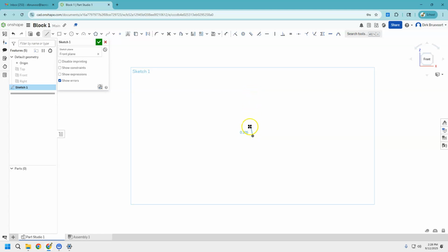Now when I'm drawing, unless I'm drawing something that's curved or angled, I'm going to always make sure that a couple of things are on. When I go up here, I can go a little bit side to side, and it will snap here, and you see it changes color, and there's that little vertical black bar. That means the line is going vertical. When I go over, it's showing that it's horizontal. When I go down, it's vertical, okay?